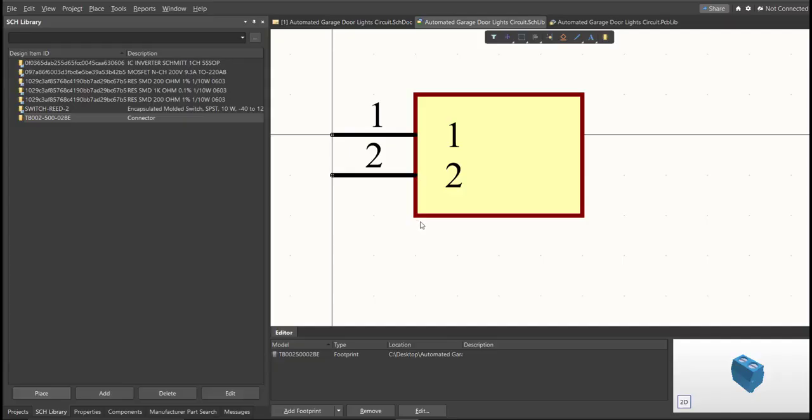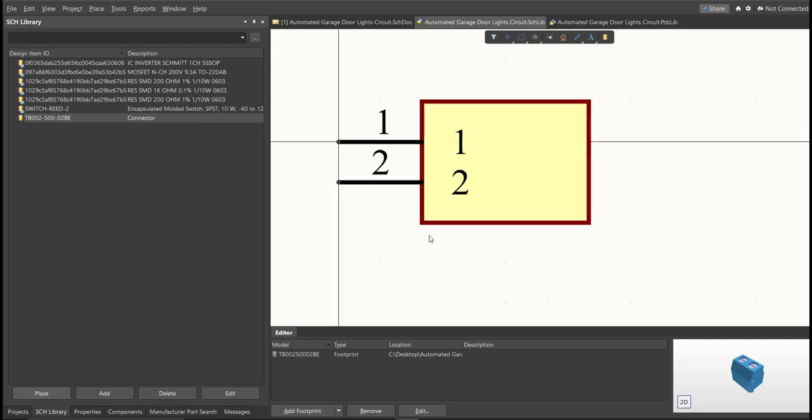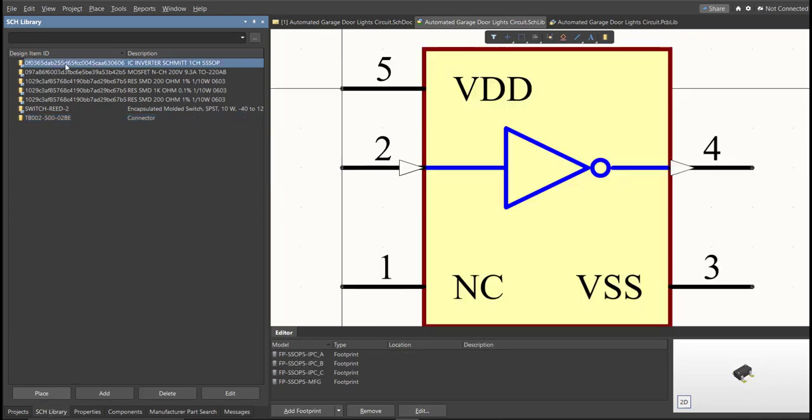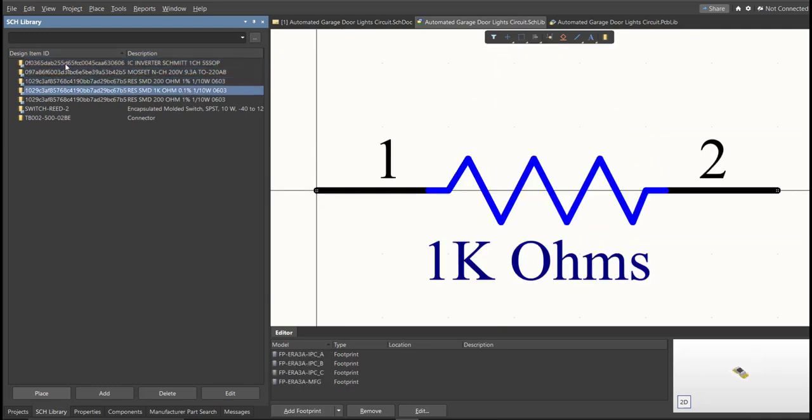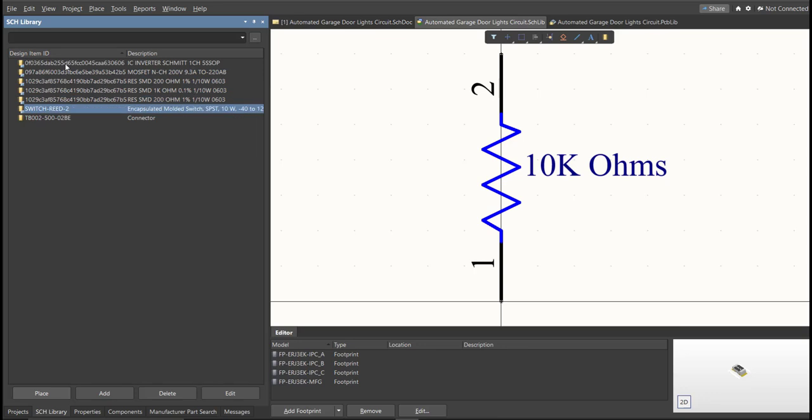After you finish all the components in the BOM list using a library loader, you can check here in schematic library panel all the added libraries. So these are the added libraries for this PCB. Next, we're going to put all of this in our schematic doc.